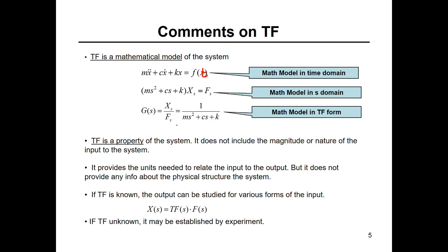The transfer function of the system, by the way, is a property of the system. It has nothing to do with the input and the output. It's independent of the input and the output. Usually, if you know your transfer function, you can calculate the output, which is the response. If you know your input and you know your transfer function, it's a matter of calculation. This is what's done in MATLAB.